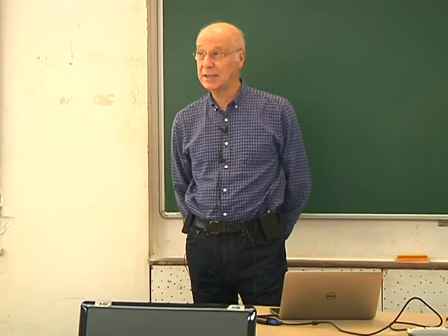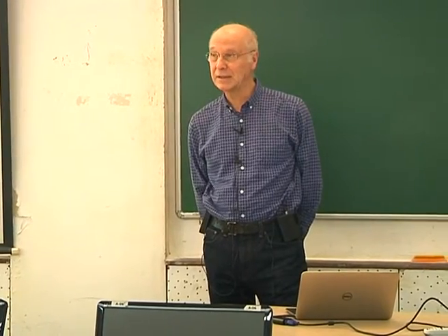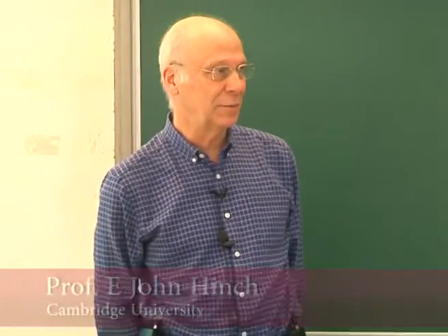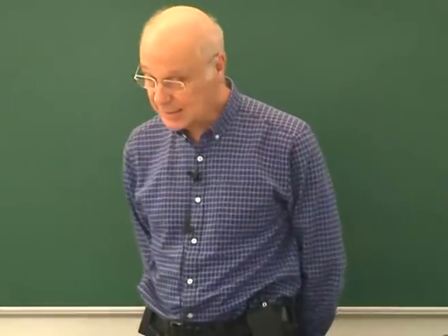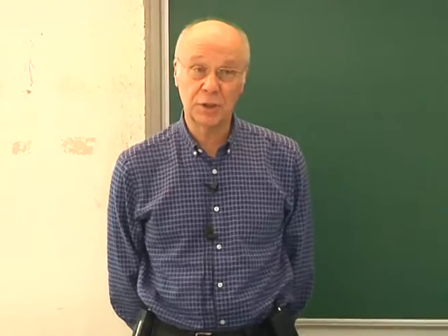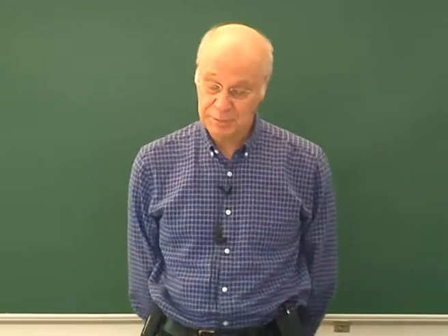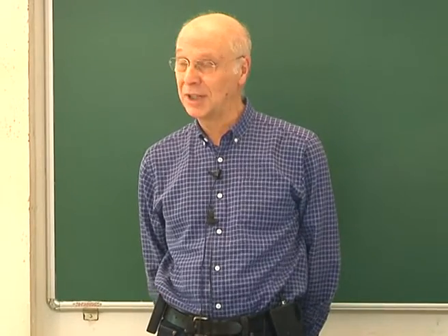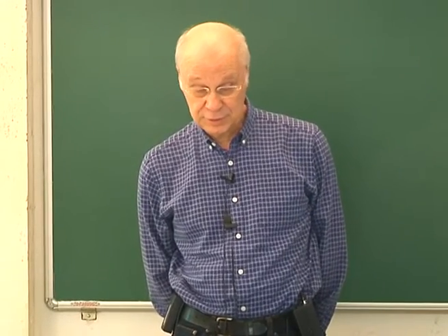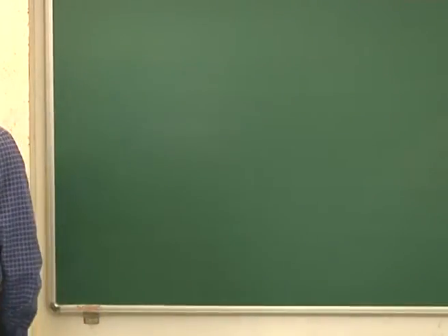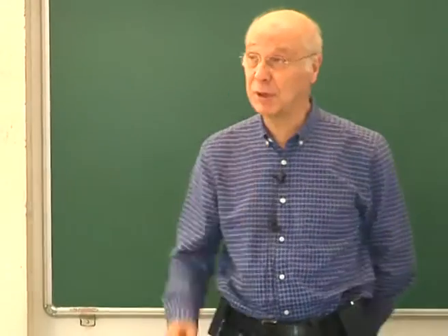These days we're supposed to be tackling a very simple problem by some very simple means. The first lecture was very philosophical about how you should generally behave yourself in tackling numerical things, the numerical approach. And the second lecture was about solving a key equation, the Poisson equation, which occurs in all approaches. We're actually using the stream function vorticity approach for the first lecture, and then we'll go to what's called the primitive variables, where we go back to velocities and pressures. And in both of them, you have to solve a Poisson problem.